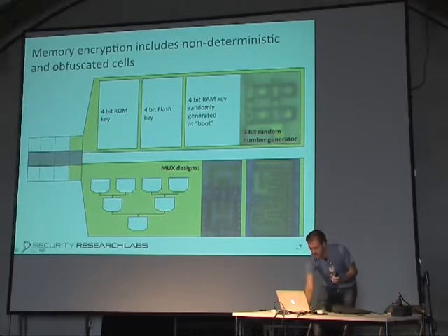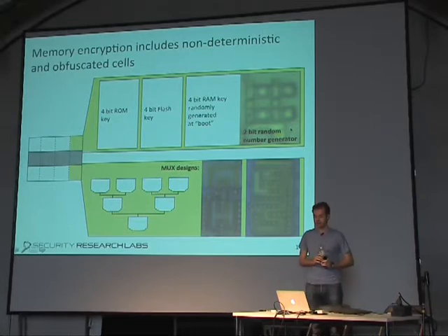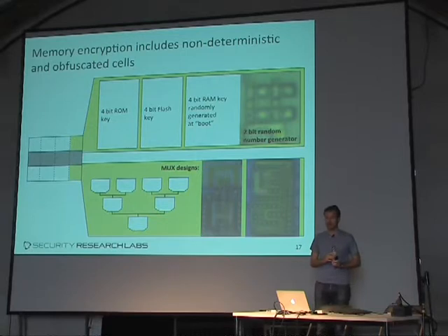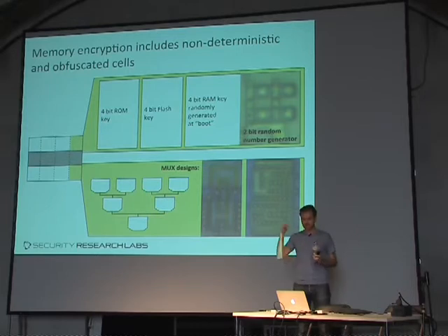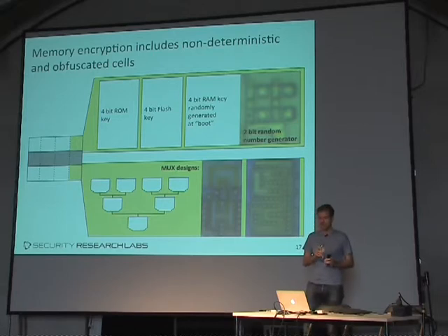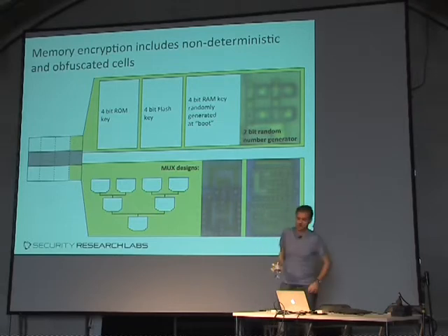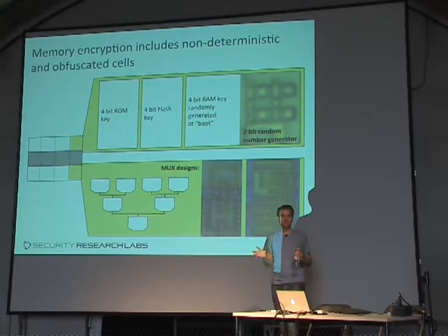And then it took me a while to figure out what these transistors do. So this is the smallest random number generator I've ever seen. Just 4 transistors to generate 2 random bits. And it does work. We did measure this with the probing needles. This does come out differently a lot of times, right? So very neat design here. However, note that they're building a really weak encryption function here, probably scarce in resources, and they store 3 64-bit keys. So a lot of the available resources are just spent on storing the keys.